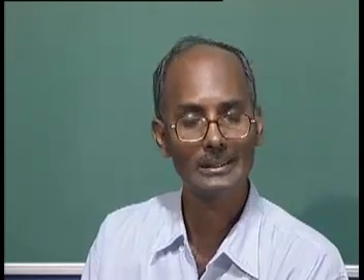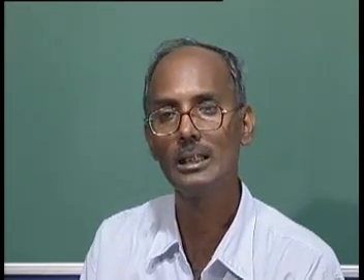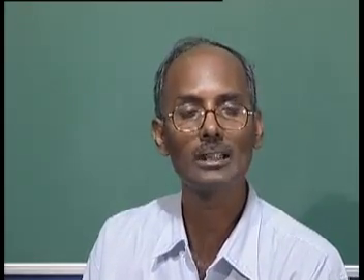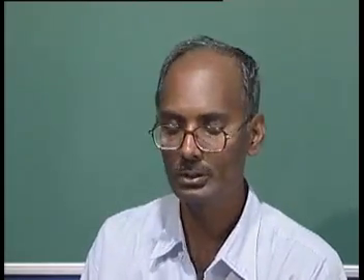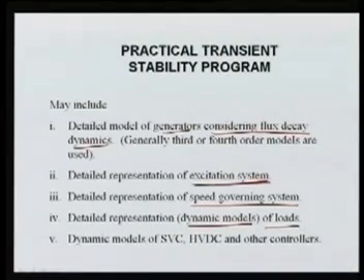If your system has some other devices, for example FACTS controllers, it may have an SVC, a TCSC, that is a thyristor controlled series compensator, a static synchronous series compensator, or a unified power flow controller. We have to model these devices accordingly and take the dynamic models of these devices to see the transient stability. If your system has HVDC, then you also have to model the dynamics of HVDC, again along with their controllers.